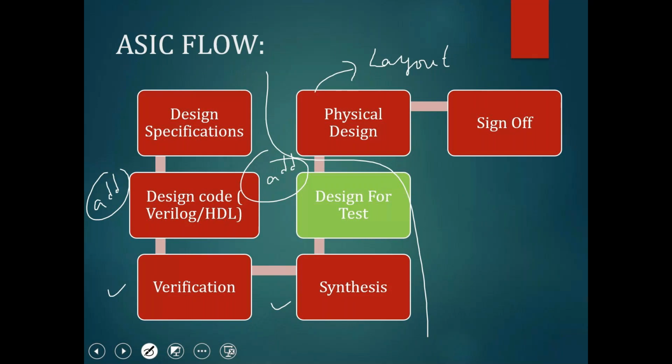So once that is done, we go for a sign off, where the timing of the chip will be covered, because you need to understand the performance of the chip also, right? So the timing will be checked here, whether it is giving a proper signal at the input of the chip, and how fast is the performance of the chip. In a way it is calculated after how many nanoseconds or how much time it takes for the signal to propagate from the input to the output, either at the chip level or at the instance level or at the gate level.